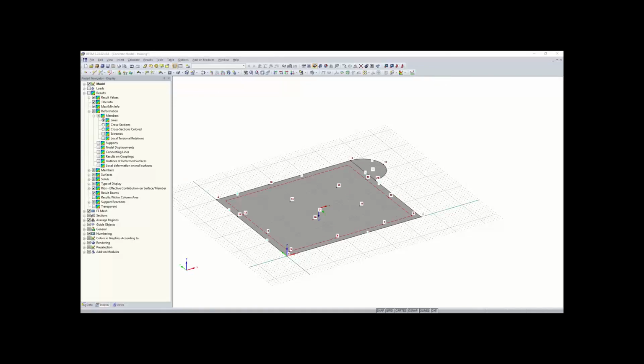And so now, after surface 2 has been created, we can work on our ceiling slab. And this should be pretty easy since our ceiling slab is going to be symmetrical, or basically the same as our floor slab. What we can do is we can highlight our floor here, and then we're going to move and copy it.